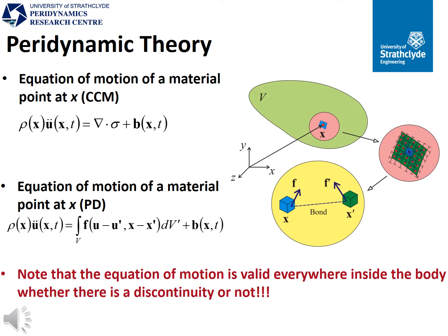In classical continuum mechanics, we are trying to solve this first equation in the slide to find deformations, strains, and stresses, and the internal forces are taken into account through traction forces. However, if there is any discontinuity in the structure, like cracks, the derivative in this term is not defined, so we cannot use this equation anymore.